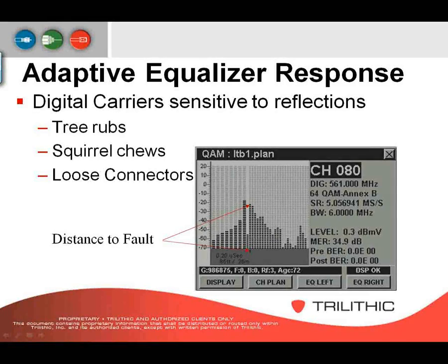Now, set-top converters have an adaptive equalizer that senses the amount of reflections and compensates for it. It's information to know how hard the adaptive equalizer is working to determine if there is any margin for system degradation.